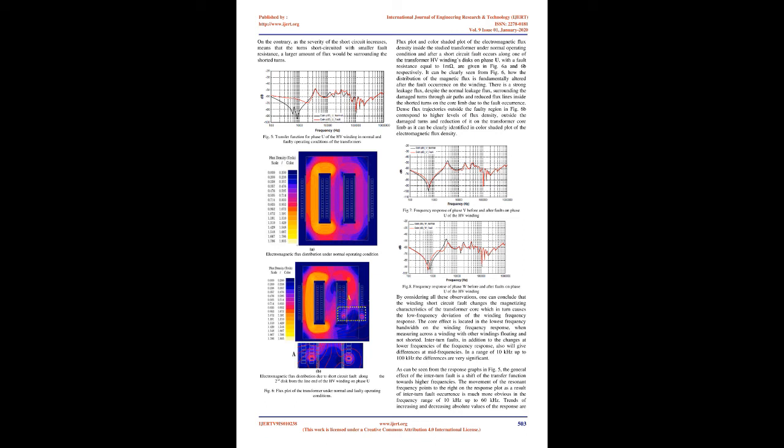3. Analysis and results. In order to obtain diagnosis criteria for detecting interturn winding faults, a fault involving 0.2% of turns was initiated on phase U of the HV winding of the transformer. The imposed fault involves a very small percentage of the winding. The smallest value of the fault resistance was chosen to account for a metal-to-metal contact and to represent an extreme value which helped to evaluate trends.